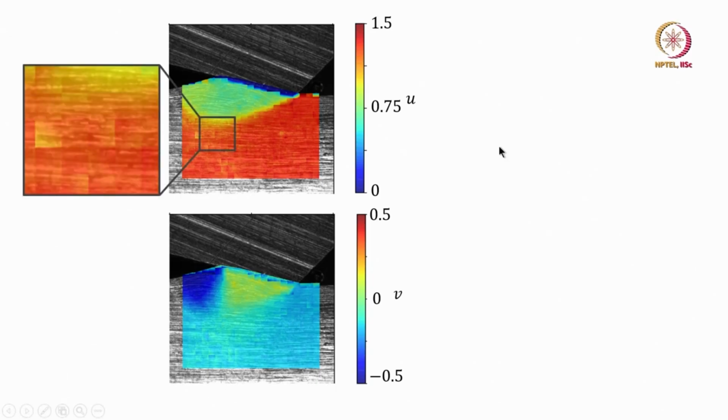However, in the solid case, if you zoom in to this field, you will see that the displacement has jumps between adjacent windows. Okay, this is the full reconstruction with the 6 component vector. So, the displacement is not constant inside each subset. You can see there is a variation going from here to the bottom left, there is a variation going within here for instance, and even in this window you can see that there is a variation going this way and so on. But the key thing is that the variation is not continuous, and you can see these boundaries very clearly in the image, right.